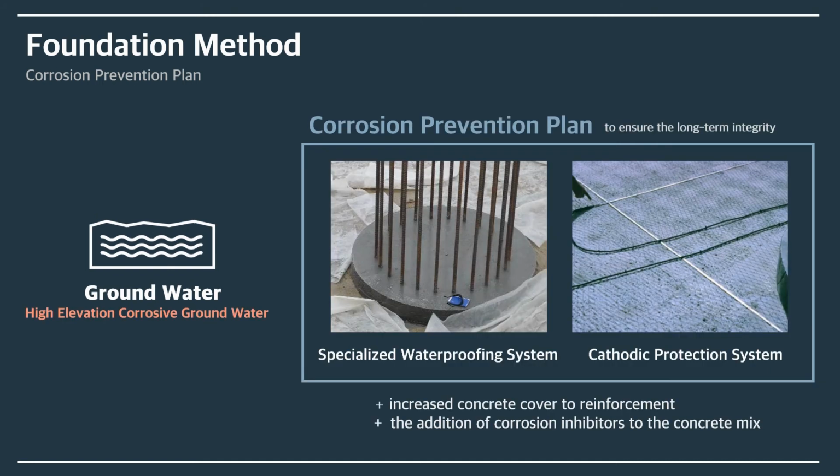But a more serious problem here is the high level of corrosive groundwater, which is about three times saltier than seawater. As such, it was necessary to have a corrosion prevention plan of anti-corrosion measures in order to ensure the long-term integrity of the tower's foundation system.